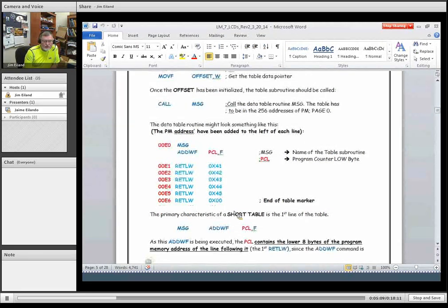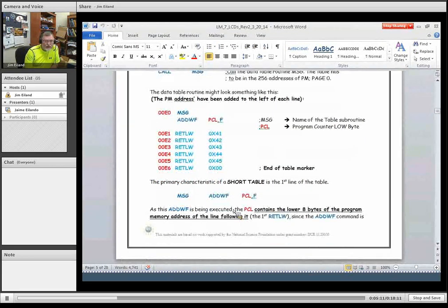We saw in the first part that the lower 8 bits will only give us 256 address locations, including 0. But you can see here we come here with an offset, and then we simply return from it, depending upon what ASCII code you want to send to the LCD. We will see that the LCD data display register needs ASCII code to actually display things.